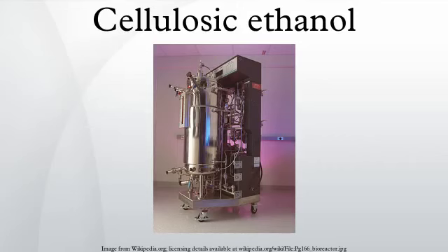The first attempt at commercializing a process for ethanol from wood was done in Germany in 1898. It involved the use of dilute acid to hydrolyze the cellulose to glucose, and was able to produce 7.6 liters of ethanol per 100 kg of wood waste. The Germans soon developed an industrial process optimized for yields of around 50 U.S. gallons per ton of biomass.